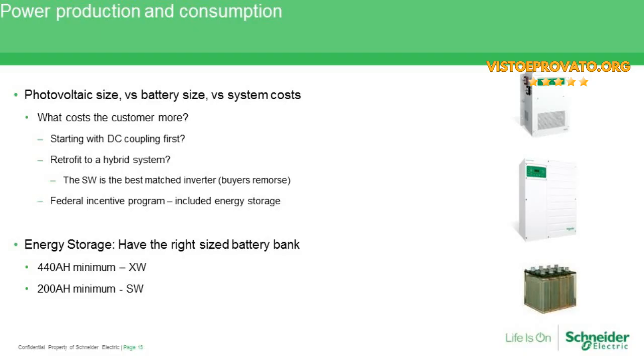For non-cycling applications with battery backup, it really comes down to when you're going to use that system and what the customer's looking for. So if they are looking for just offsetting a power bill with, let's say, net metering and that's it, well, great. But if they are looking for something that they want to have backup power and they want to be able to have some versatility for now and into the future, then doing DC coupling from the beginning, I would argue, makes the most sense. But there is always, of course, that option for AC coupling later on.